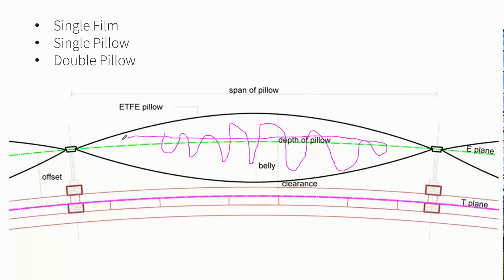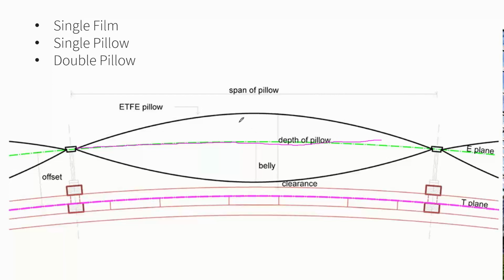They blow in air through these pillows through the whole thing to keep it inflated. Or you can try to get an even better system with better U values, and they would put in a 3 film system. So it almost mimics a double glazed unit with 2 air pockets.